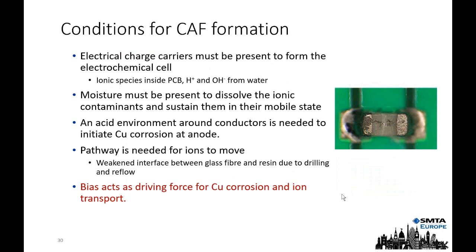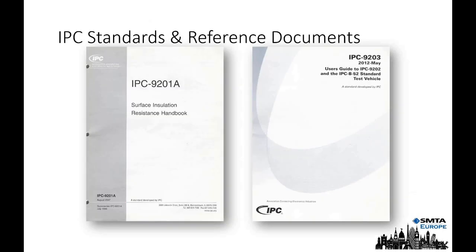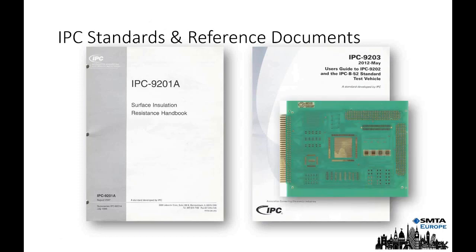with my good friends at NPL, and what I've been doing is doing some testing on board assemblies, and I'll report this. So basically with SIR testing, we're looking at a standard board which is well known in the industry, and what I did is took this printed circuit board and added test patterns to it.